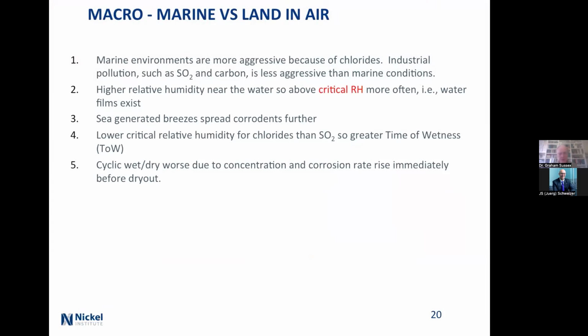Higher relative humidity near the sea, so it's going to be above the critical relative humidity. That's basically the relative humidity that's high enough to make the salt dissolve. And so you get water films with salt water in them. Sea-generated breezes, well, they're going to spread the corrodants further. And if you're talking about chlorides, then critical relative humidity is down around 50% or so, whereas with sulfur dioxide, it's up around about 80%.